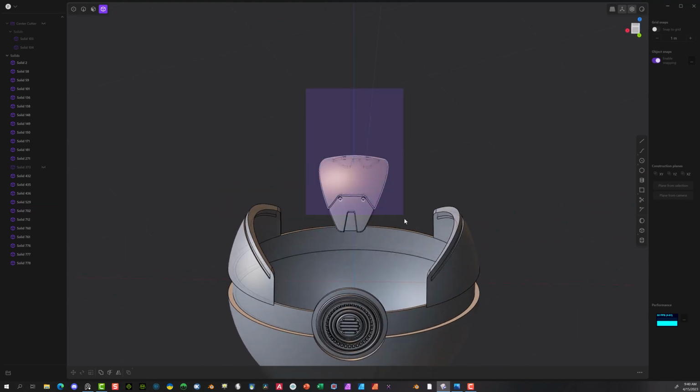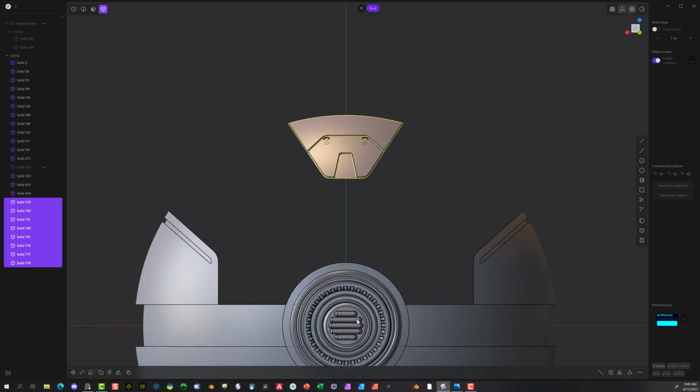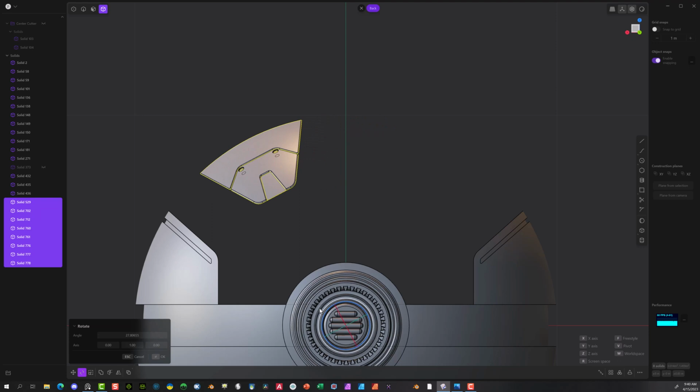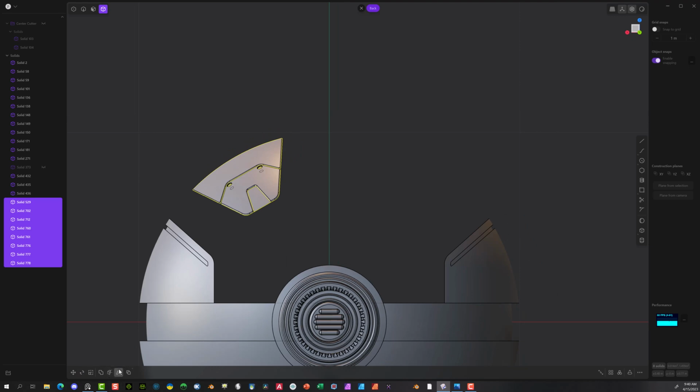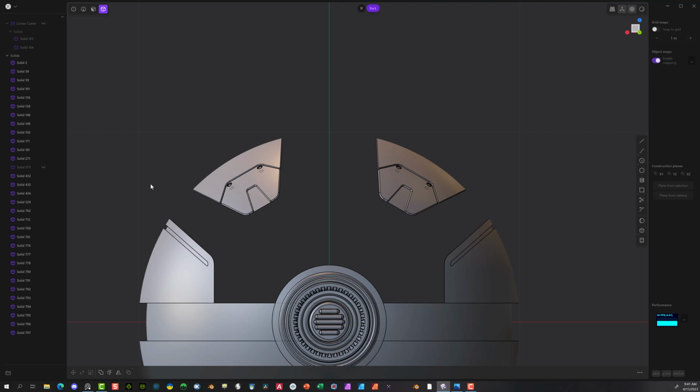I'm going to select all these. Go to your y-axis. Make sure everything's selected. And now I'm going to rotate it again. And make sure that's on the, hit the V on the center. And go back 30 degrees. Rotate, V, center. Go ahead and type in 30. Now we've done that, we could mirror this to the opposite side, say okay. Cool. So now, one thing I'm going to be doing is I'm hiding this one.